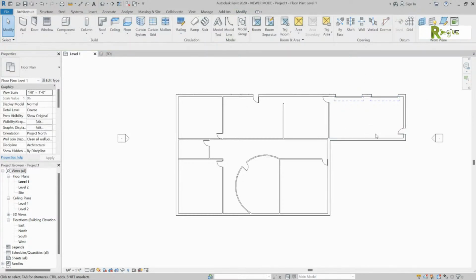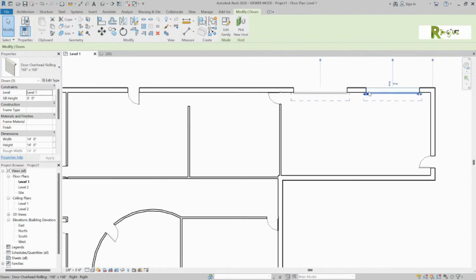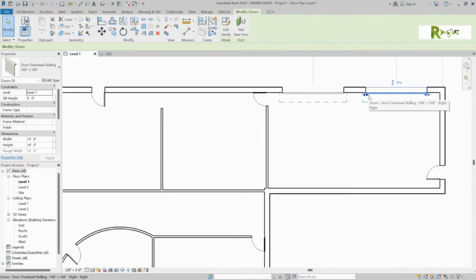You could also pick on that door. When they created that door, they put flip controllers in it. Do you see those little double arrow looking things? The ones up on top of it. That's it. So if you wanted to flip the direction or flip the side, you can flip by clicking on there. But remember, I told you that space bar is going to come in real handy with lots of things, even structure and mechanical.